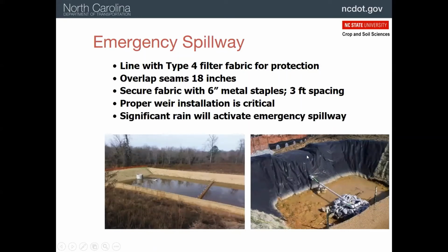And then we have this weir. If we have a lot of rain and this basin fills up and the skimmer can't dewater very fast, then it will start to go through this cut in the dam. The weir's width here is specified on your plan. The size of the pipe and the orifice we'll get to on the skimmer is specified on the plan, but also the width. Bigger basins or more flow expected will have a wider cut in that dam.